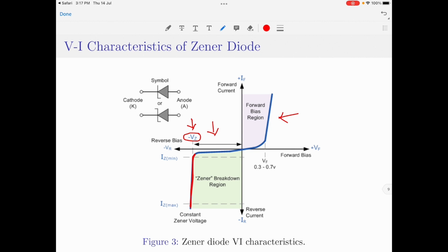So, in practice, we can say that Zener breakdown occurs at a lower voltage as compared to that of an avalanche breakdown, and this is mainly because Zener diodes are purposefully doped for the Zener breakdown. It should also be noted that the Zener voltage of the diode gets adjusted during the manufacturing process with the help of a required level of doping.